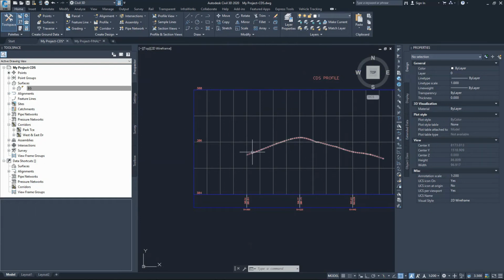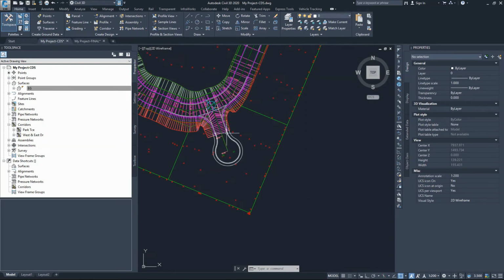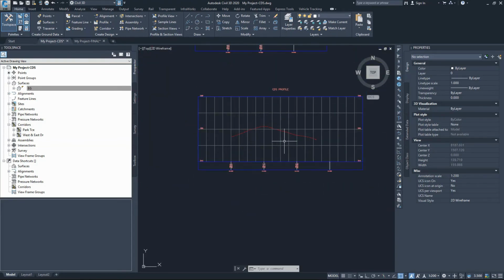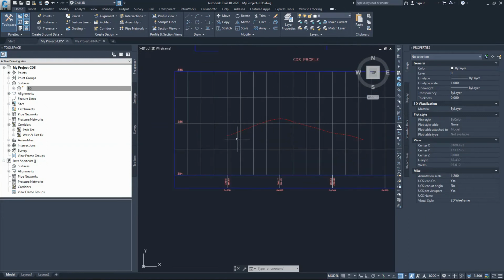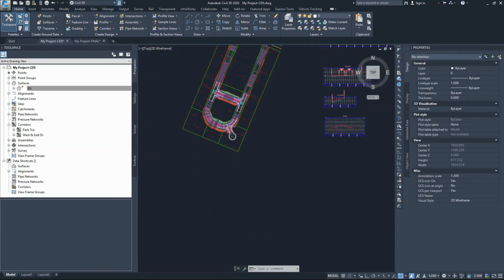Very important to understand, this is a curved line profile, so it's not the road. The road goes just like that, but this is where the curve is going to go, around the edge of the Cul De Sac. The reason I'm saying this is the curved line, so I don't have to follow the road design rules about the K values, about the size of the curve and all of this. This is a small road, there's no worries about the K values, about the radiuses and the size of the curves. Okay, so we created an alignment, we have the surface profile for that.